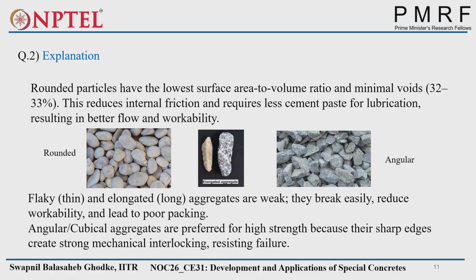Okay, but in the case of flaky and elongated aggregates, these aggregates are weak because they break easily, reduce the workability, and lead to poor packing. The main thing is that poor packing. The strength comes from the packing and the calcium silicate hydrate binding in any type of concrete.